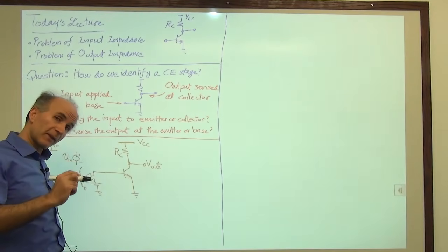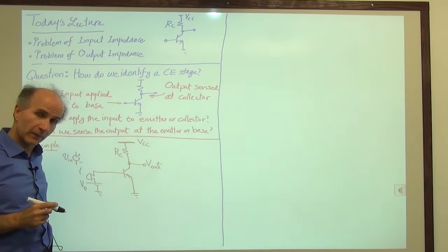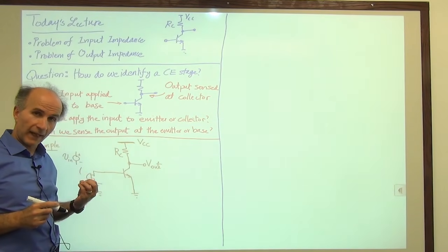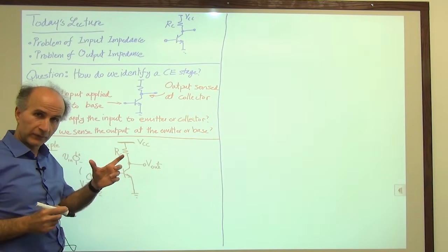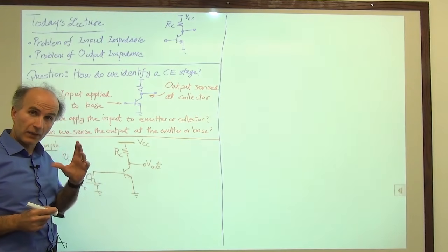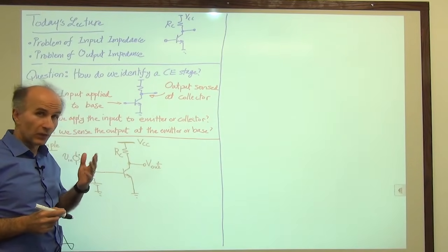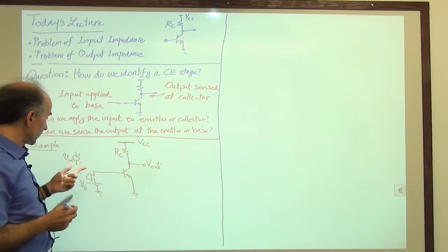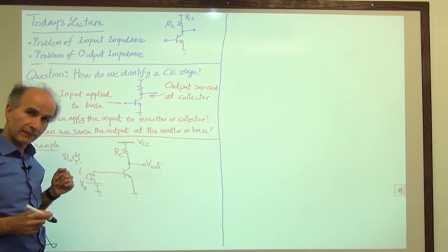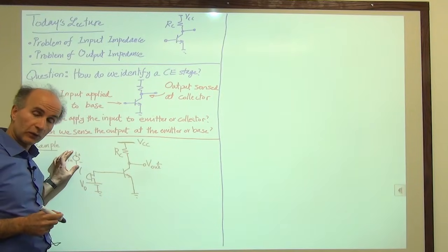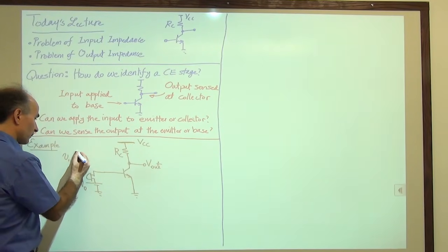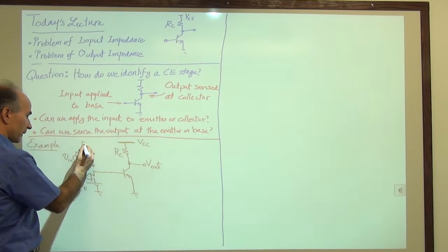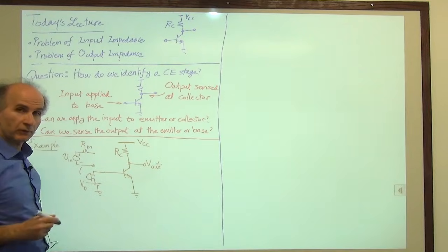If you remember from basic physics and basic circuits, we said that, for example, a battery has an internal resistance, meaning that if you have a battery of 1 volt and you connect it to a resistance of 1 ohm, you will not get 1 ampere because the battery has an internal resistance. Similarly, a microphone has some internal resistance. In other words, it's not an ideal voltage source. So a microphone actually looks like this. This is the model of the microphone. We'll call this something like RM for microphone.